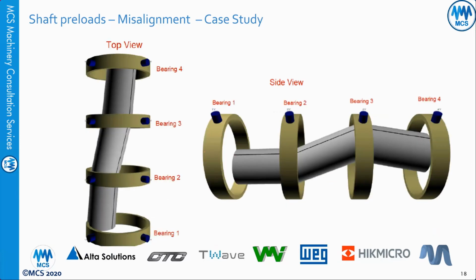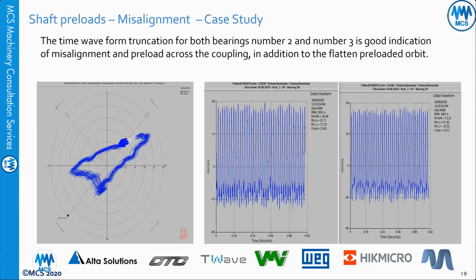Yes, an uncentered time waveform like this one. Do you mean the time waveform is not symmetrical? Yes, this is an indication of preload, because the maximum amplitude from zero is different from the maximum negative amplitude from zero, because of the movement restriction. Unbalance itself can be considered as some sort of preload. A quick example: I did balancing for a steam turbine before, and vibration levels dropped massively. Then when we ran the turbine again, we got oil whirl.